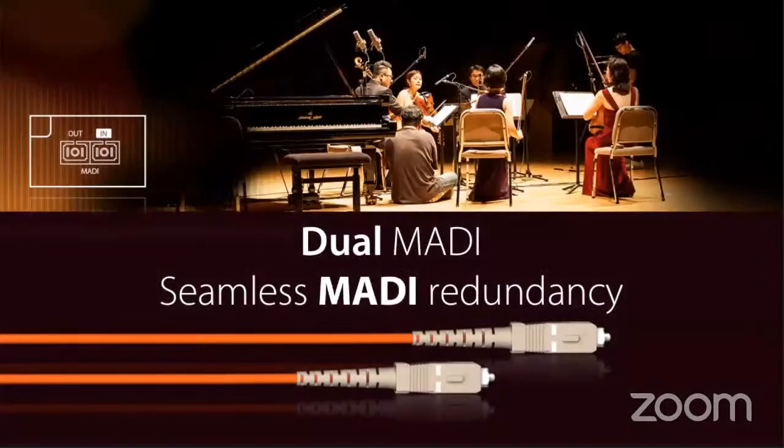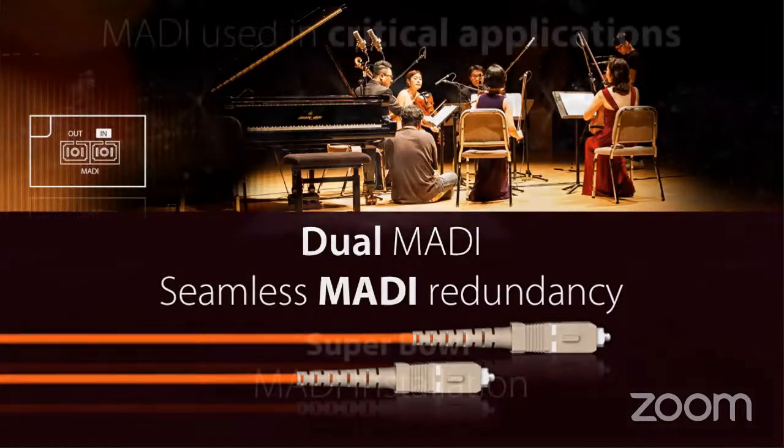MADI does have a very powerful feature, which is seamless redundancy. So you can have on several hardware MADI devices a primary MADI IO and a secondary MADI IO. And you can set your receiving device to basically look at both the primary and the secondary. And if something happens to the primary stream, then the secondary stream takes over. And the idea is to do this without it being perceivable by the audience.